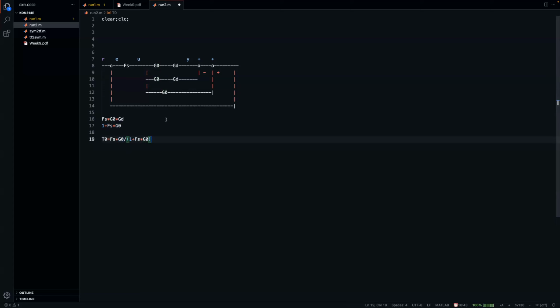So the Smith predictor comes up with a structure so that you will use the non-delay part, you will neglect the delay part, the structure will handle delay. So you will have basically only 12 divided by s plus 4 times s plus 6, without the delay, without any Bode approximation. You will just use G0 to design your PI controller for 10% overshoot. Once you have done that, you will use that controller and the special structure and you're good to go.